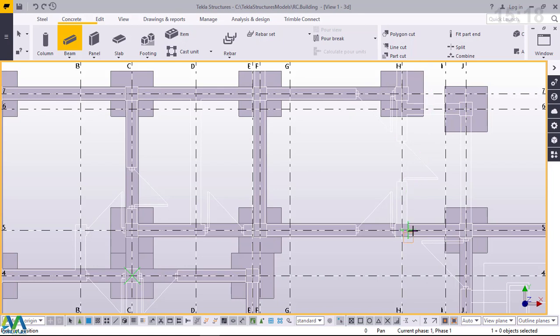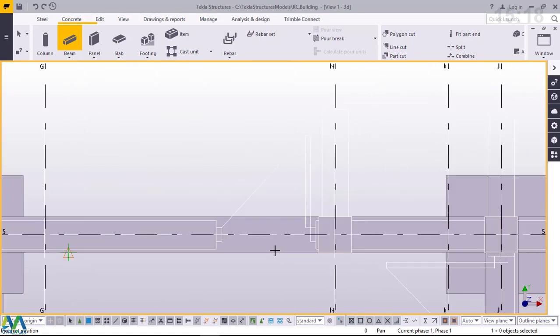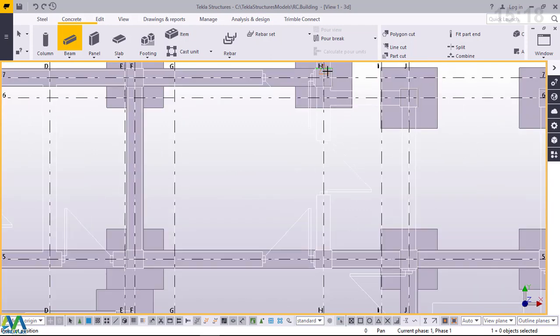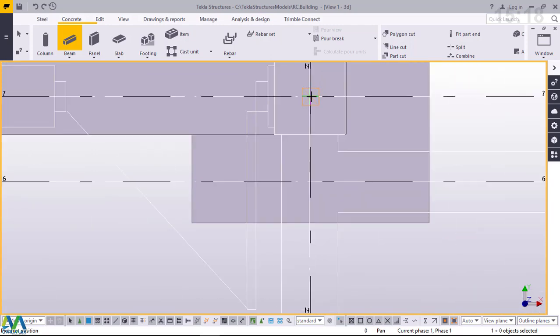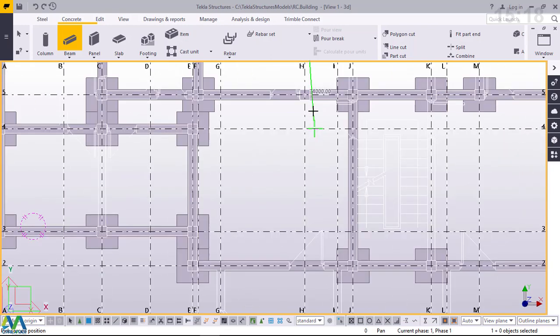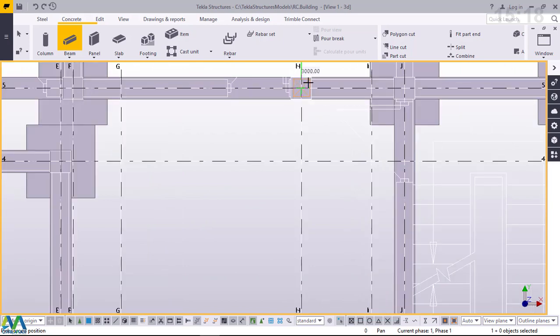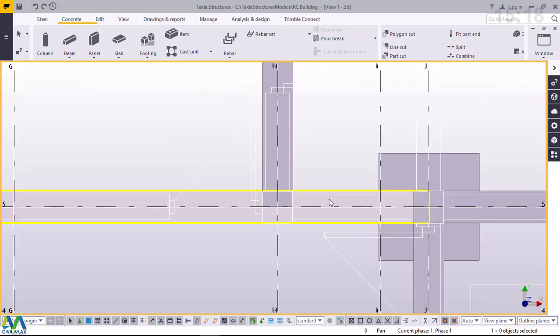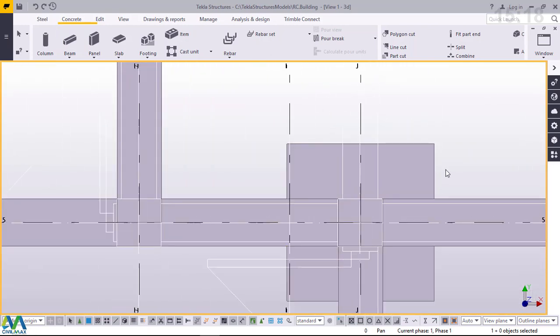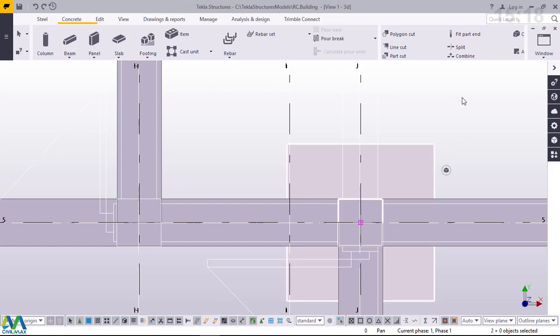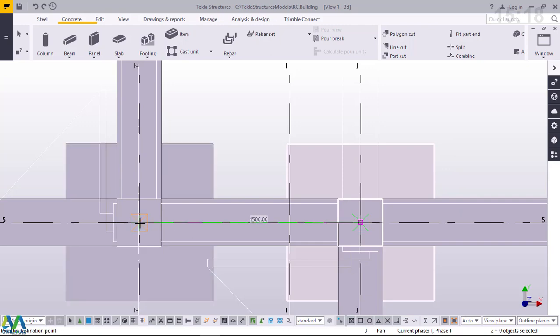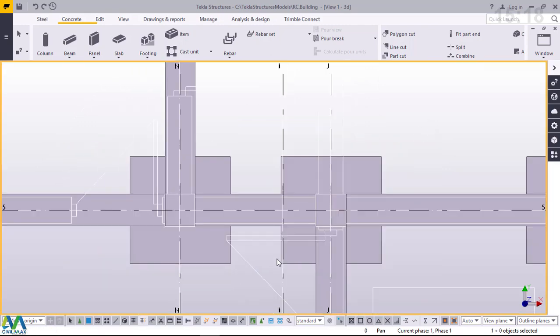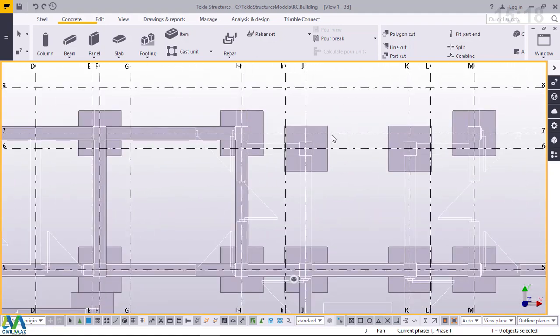We didn't place any column here, and first of all, we'll just place our beam first. We'll just place our plinth beam because the beam will be placed in the right position, already set. Then we'll come later on and place our pad footing. Now I'll just do it right here. I'll press Control, then I'll come to copy and pick that from that position and place it here. Perfect. It has been placed. Then I'll click right there just to deselect that.